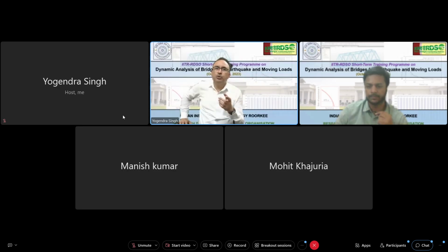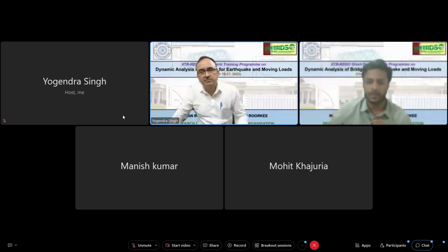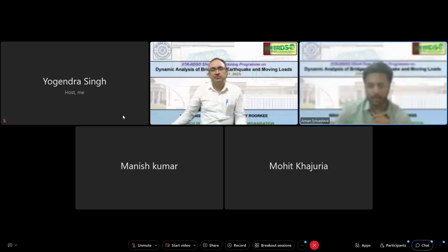But what will happen if both people have used different sets of ground motion? Their answers are going to vary. That's why we need a standardization of the selection process, so that anybody analyzing that bridge should come out with the same response. Otherwise, different people can come out with different designs, and in one case it may be safe, in another case it may be unsafe. Sir, we'll take the last two questions now.